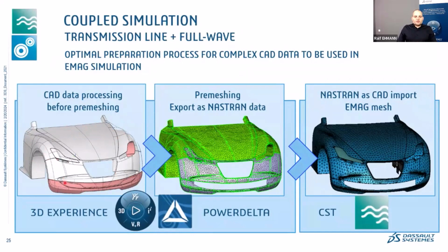So I just wanted to mention here that in the ideal world, the CAD data which comes from the mechanical designers will be perfect. If the simulation engineer sees this model, he sees that all electrical connections between the parts are done as they are in reality, as he expects. He doesn't have to make any additional changes or make sure that everything is connected. He does not have to remove unwanted features and details inside that CAD data in order to simplify it and run it almost optimally.